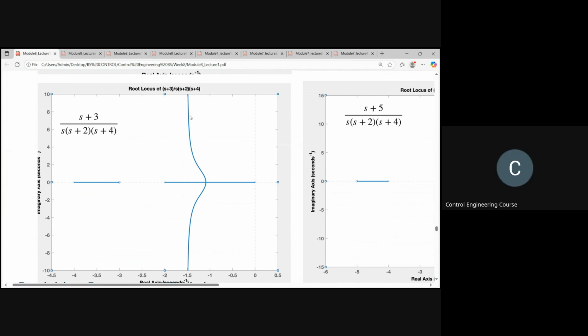You need at least 4 or 5 times, right? The third pole starts at -4 and ends at -3, so if k is very high it will go close to -3, but that is just 2 times -1.5, which is not enough to be a dominating pole. So this also fails.